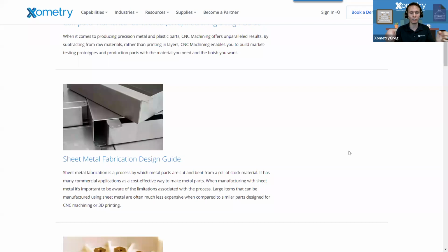That is going to be, if I have 2 holes because I'm going to be laser cutting, actually a laser cutter's tolerance. There's the thickness tolerance, which is actually the raw material stock tolerance, and then a bend feature tolerance, because bends themselves are a little tricky, and there's always a little bit of variability there. So understanding where and how to expect different tolerances in designs is really big, and also helps you better understand how to make a drawing for sheet metal parts as well.